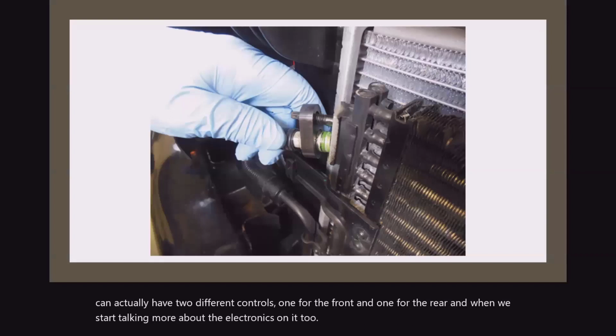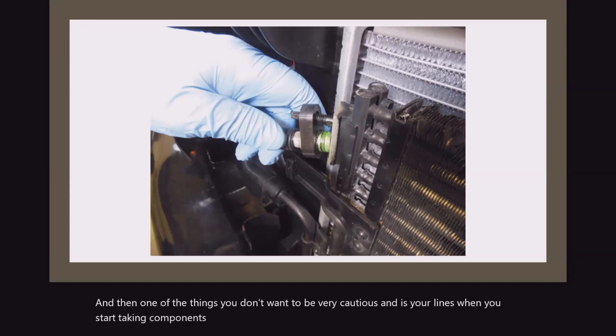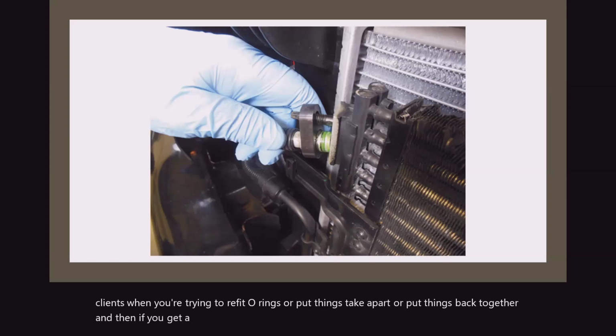And then one of the things you're going to want to be very cautious of is your lines. When you start taking components apart, make sure you follow procedures. You can actually kink lines when you're trying to refit O-rings or take apart or put things back together. And if you get a kink in it, then you've got a little bit of restriction. So that's another concern.